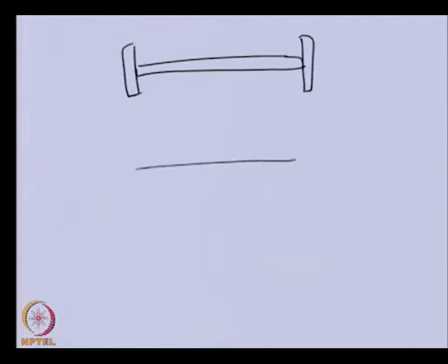If we get the mode shape, let us say one of the mode shapes has one node here, and let us say the gear position is here and the node is here. This is for the equivalent system. If we want the mode shape for the actual system, the angular displacements phi Z1, phi Z2 should be divided by the gear ratio.